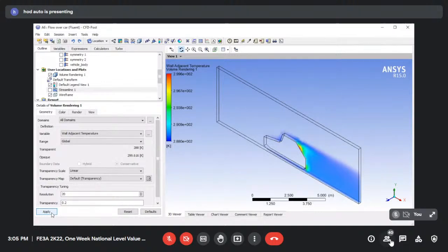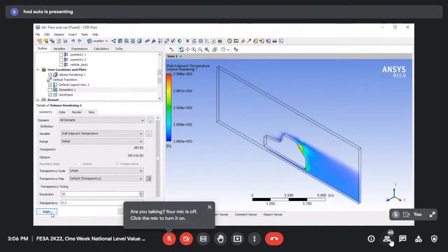And mind you, if you talk about a vehicle moving at Mach 1 or Mach 2, supersonic missiles, cruise missiles, enormous amount of heating is observed on the surfaces. You call it ablation, self-sacrifice of the materials happens. And this is a small situation wherein you have a temperature of 296 Kelvin from 288, localized heating. It can be taken up.